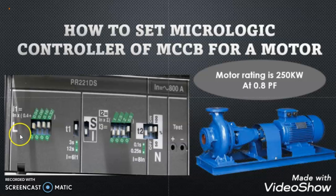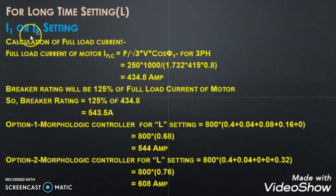As the L setting is for the overcurrent setting, we will first calculate the full load current of the motor, and based on it, we will set this L setting. The full load current of motor formula is P divided by root 3 into V into cos phi for 3-phase.